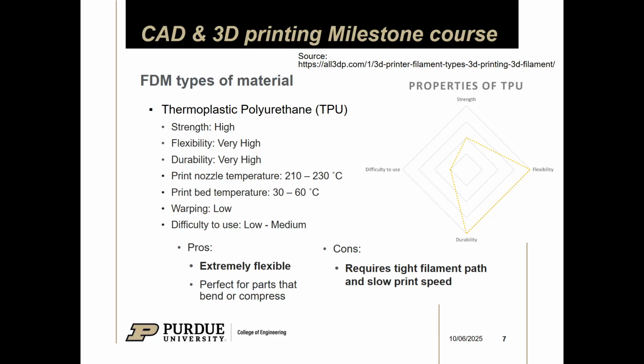If any of you are into battle bots, a lot of people who 3D print their battle bots in the Antweight class use TPU for their shells, because it's so flexible and very impact resistant. They can take a lot of abuse, and their battle bots can last a long time. So again, different use cases, different materials. It's pretty fun stuff. Typically for TPU, you have to print a lot slower because of how flexible the material is. It used to be a big challenge back in the day, but it's not really the case anymore. Most machines can print it. It's pretty cool.